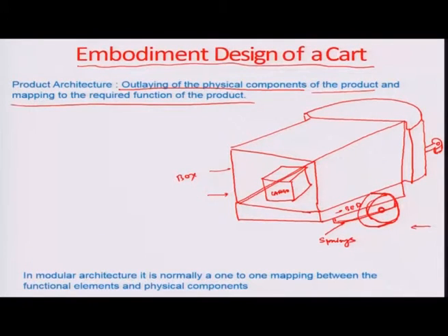So, you have a cargo here, we have a box, okay. You can see the box right about here, there is a bed, there is a spring, there are certain wheels which would be the load bearing members, there is a fairing here just for reducing the aerodynamic drag, and then this is the hitch which will be used for pulling the cart. This hitch is attached to the end of a power provider, it could be either a tractor or some kind of a small engine driven mechanism which would carry these cargoes, so sort of a cargo vehicle from the airplane to the main station or terminal or back.